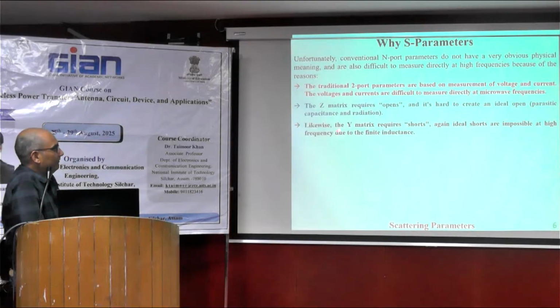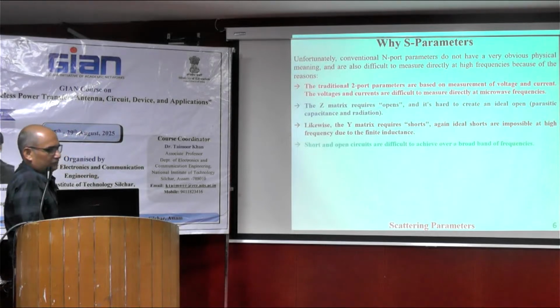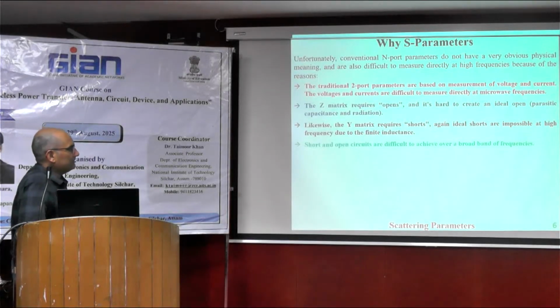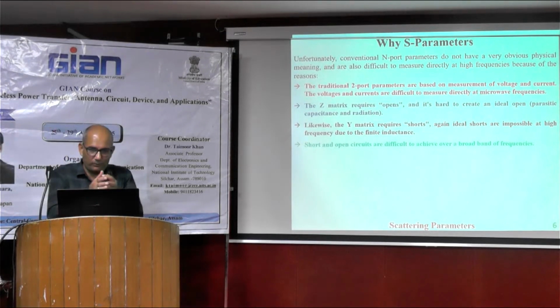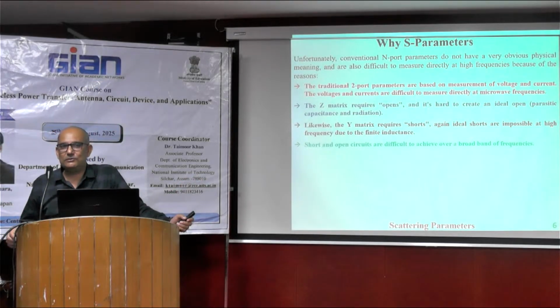Likewise, Y parameters require short circuit conditions. When you are making a short circuit condition, again it will be a problem. Ideal shorts are impossible at high frequency due to finite inductance. That is another reason. And the last one, short circuits and open circuits are difficult to achieve over a broad band of frequency, because in high frequency we need to play with the frequency, not with the voltage.